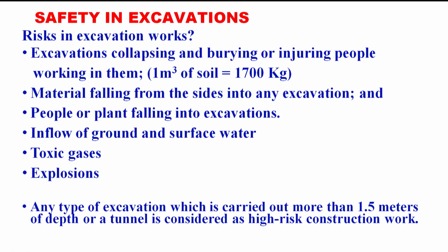Then next is toxic gases. This is also very important. When we are excavating deep, there may be some pockets inside the ground which have toxic gases. So proper survey should be done, and care should be taken if there are chances of having some toxic gases in that area. So proper masks and filters should be there, which the workers wear while they are doing this excavation.